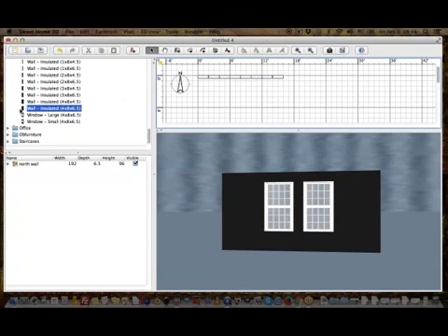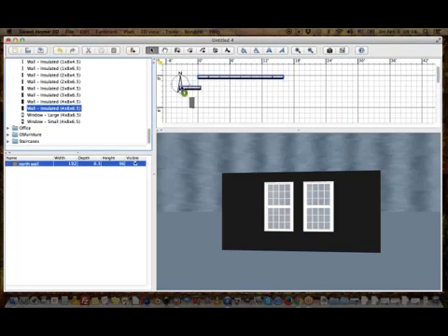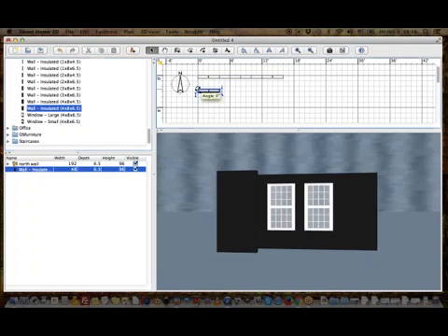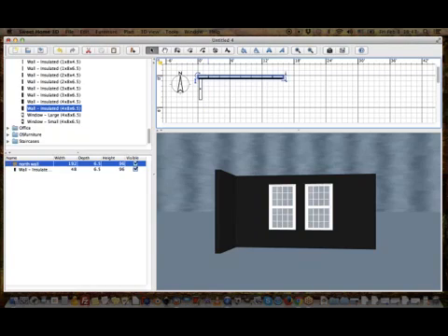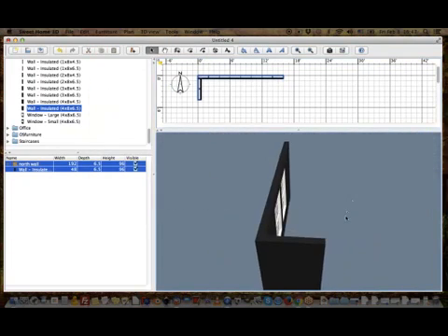Now I need to do a side wall. So I'm going to take another wall module to do the side wall, and I'm going to rotate it because I want it to be here. Okay, so now you see, when I use it like this, it snaps to the other one. So it's fine there, but I need to align it on the left side. So I'm going to start by selecting the one that is in position, or even the whole group, and then selecting this one and do align on left, and boom, now it's perfectly aligned.